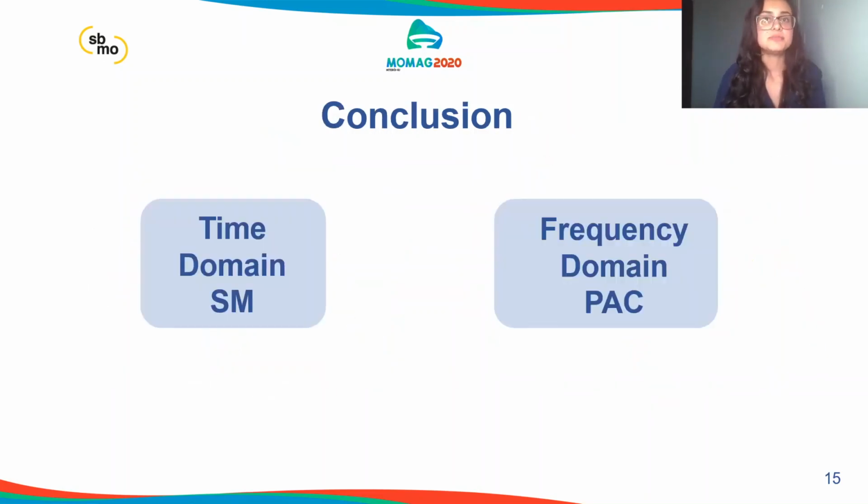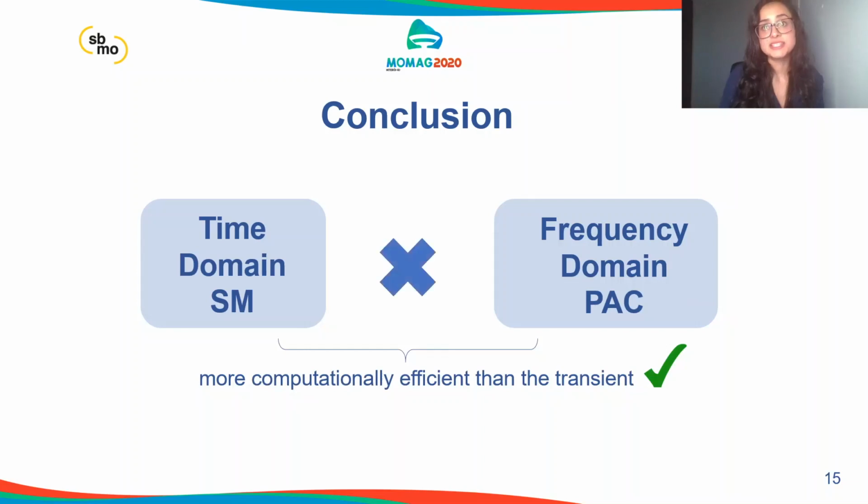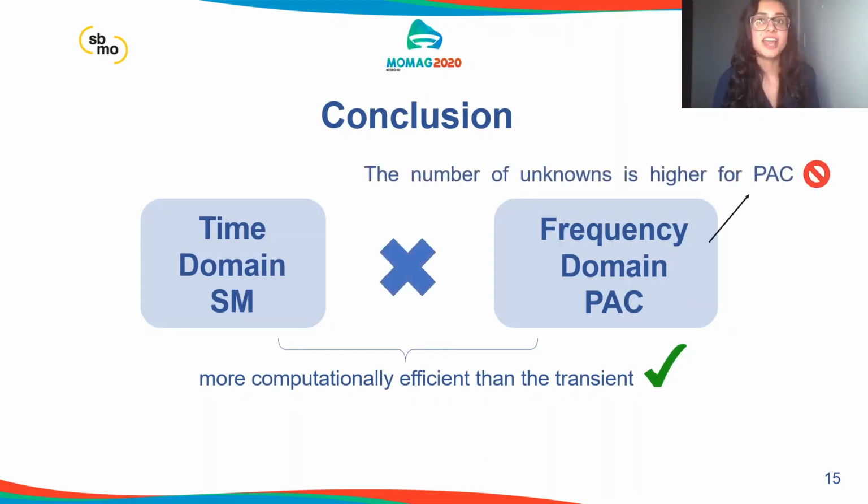From the comparison between both approaches and the commonly used transient simulation, it can be concluded that both methods, generally implemented in radio frequency circuits, can be used in nonlinear low-frequency dynamic circuits, such as those found in the power system. Considering their iterative process, they are more computationally efficient than transient, mainly for a serial inclusion of sources injecting harmonics in the circuit.